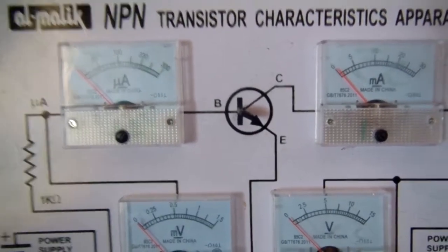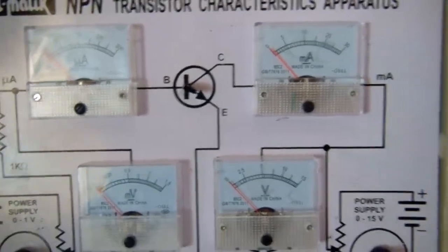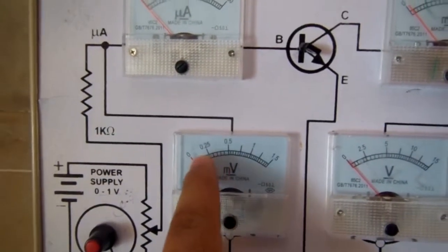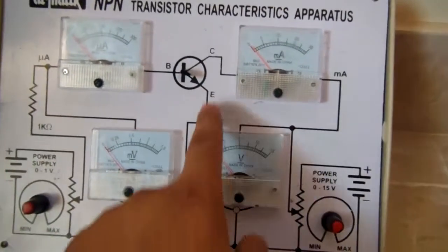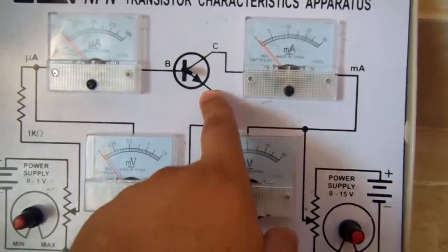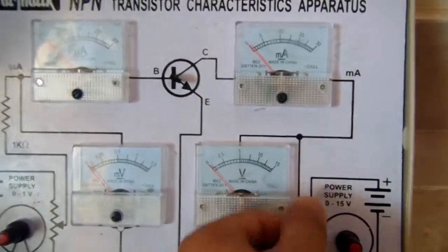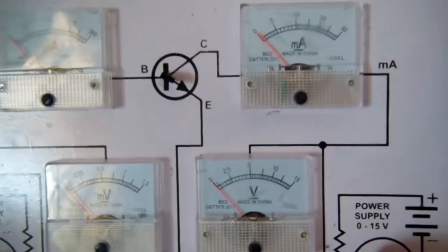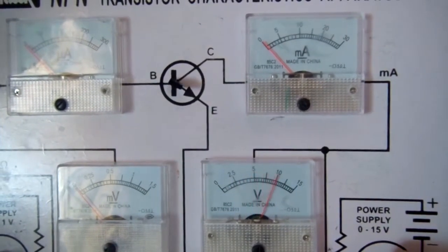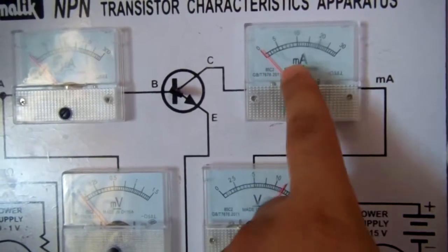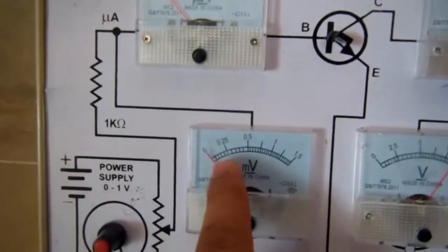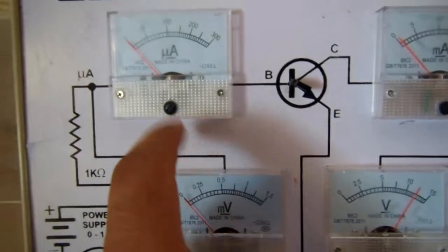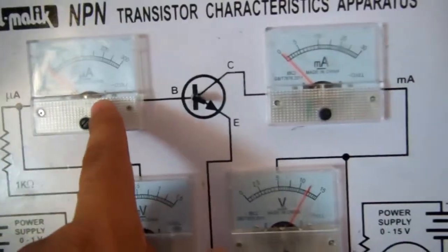There are three modes of the transistor. Here, when the base voltage is 0, the base current will be 0. If you increase the voltage across collector to emitter, there will be no change and no increase in the collector current. As you can see here, we are increasing the collector to emitter voltage, but IC does not increase, because the base current is 0 and the base voltage is less than 0.5 volt, so the base current is also 0 ampere.